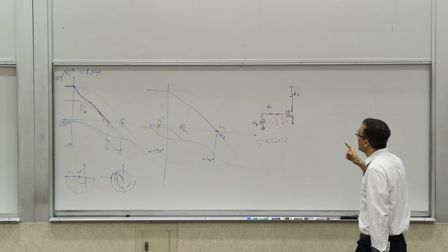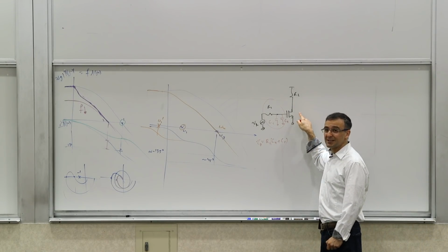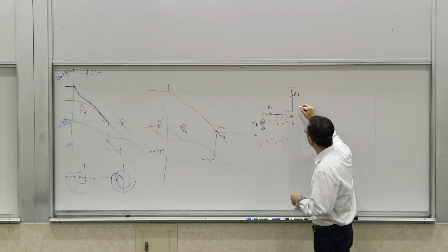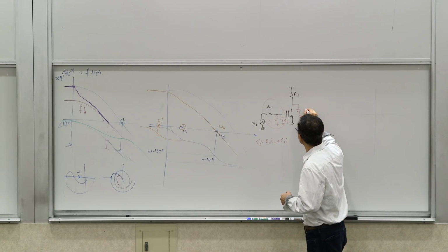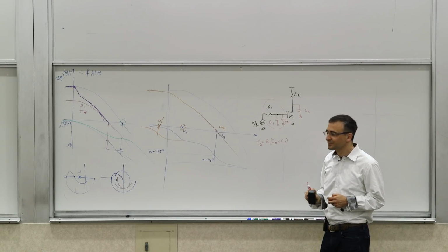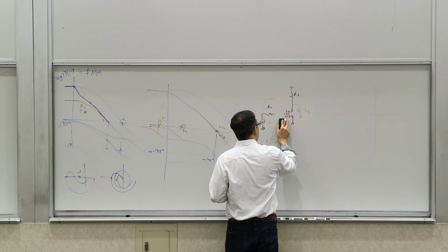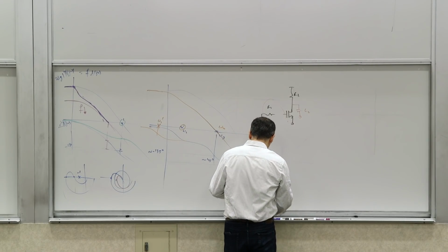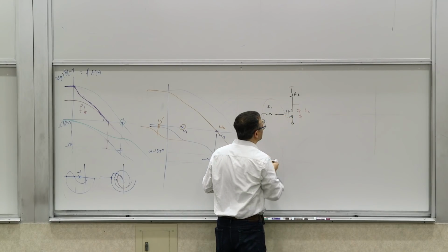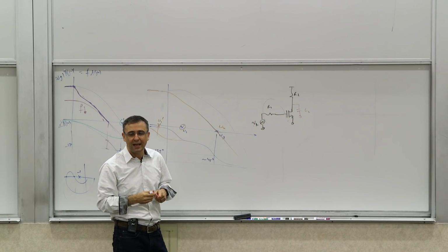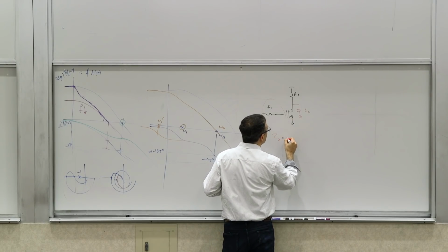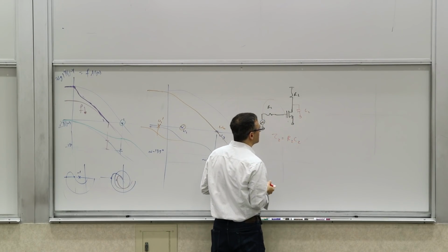Now, we'll see there's actually another way. If your capacitor was at the output, at R2, it would do something interesting. So let's talk about that. That's probably an even more interesting question. Let's say this is C2. Let's say that instead of going through R1, I have an output capacitor, C2, and if that was the only dominant time constant, then in this case tau 2 is R2C2, right?